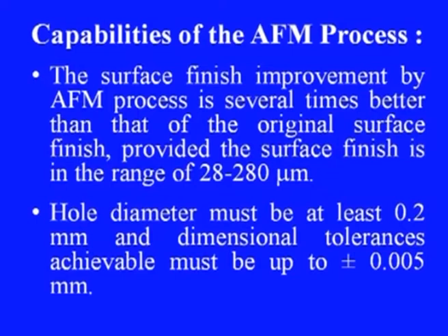Hole diameter must be at least 0.2 millimeter and dimensional tolerances achievable are up to 0.005 millimeter. Very fine holes will not get better finish because the restriction of the hole will not permit the free flow of the abrasives into these narrow zones. Thereby, we may not get expected results in case of very tiny holes.